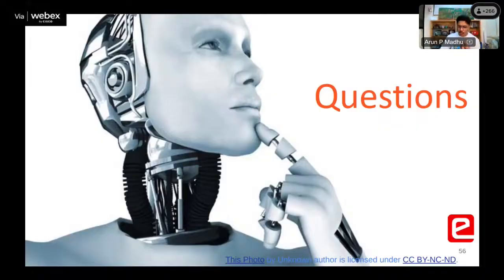Does a drone use a PID algorithm? Yes, a drone uses a PID algorithm. The firmware of the drone contains inbuilt PID algorithms. So when you give commands from your transmitter or remote control, those commands go into the firmware, where different PID algorithms work in order to balance the drone.